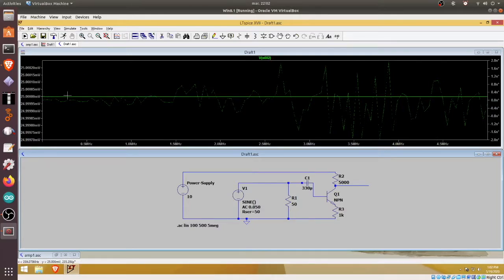We're getting our 25 millivolt response. If you're wondering what these dots are, this is the phase measured in degrees here. And as you can see, the phase is very close to 0 degrees, which would be a perfect response. So that's completely fine. It's a flat response. So the input is at 25 millivolts. I mean, it's really at 50, but we are reading 25.